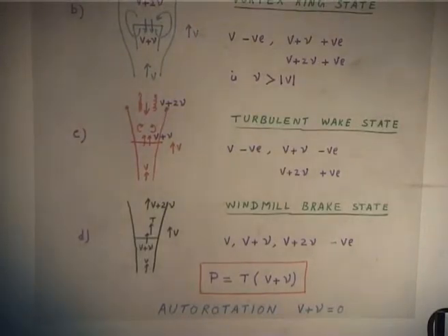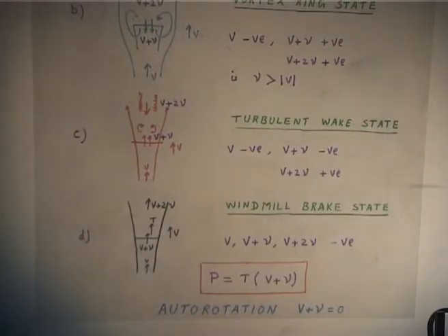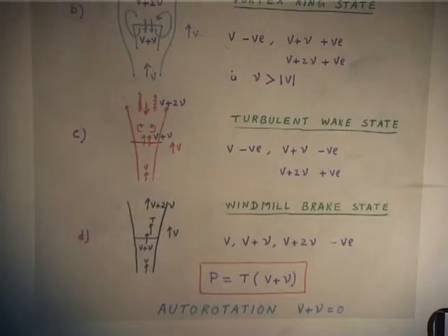If you come with the descent velocity, you normally, helicopters, I will tell you, the moment you come to this condition V plus nu 0, that means the power required to rotate the rotor is 0. You do not need engine power. Okay. Of course, if there is a profile drag, you descend with that, leave it. Assuming, take it as an ideal condition, you do not need engine power.